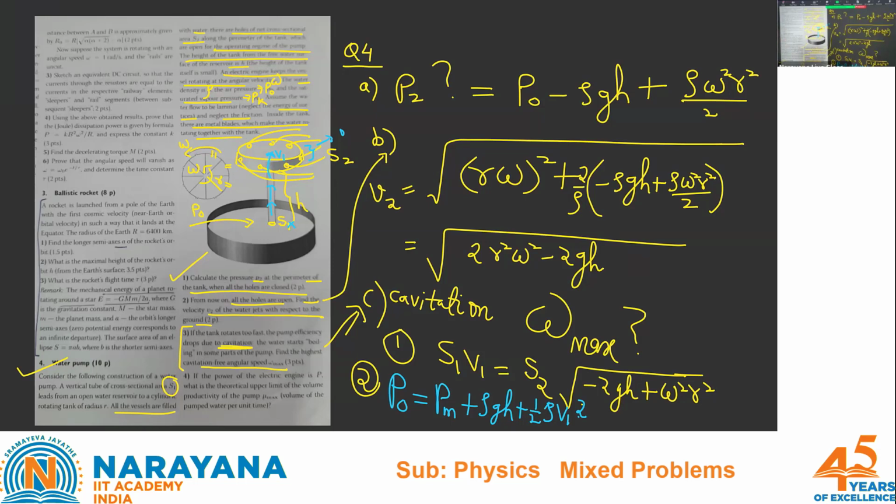This much is fine. Solve these two equations. Substitute your V1 here and try to find out PM. The matter of fact is, why I'm interested in that PM, in this configuration, the least pressure, when he says find out the highest cavitation free angular speed, so the statement is that the least pressure is actually at the PM pressure. I mean, in the upper structure, at the center, on the axis of that structure, the pressure is the least. Already P naught is decreasing up to that point, and afterwards it is increasing. So that is the least pressure point.